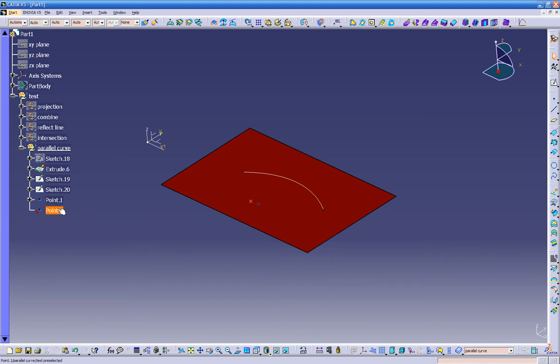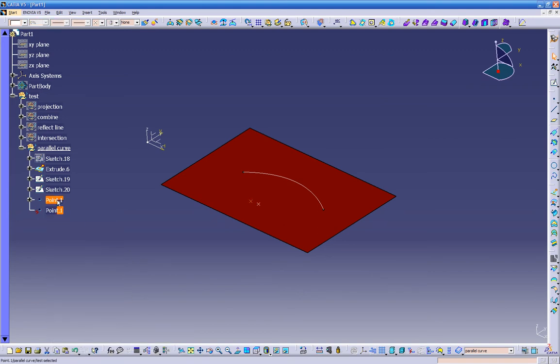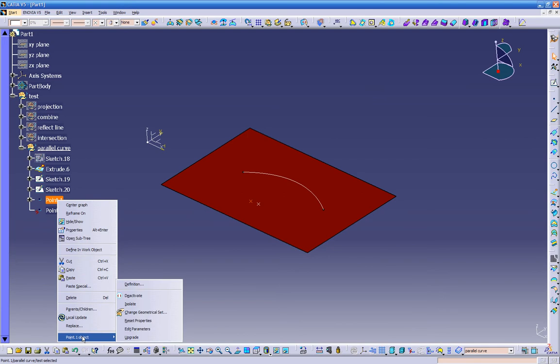So it's all standing alone. That's why when I build my geometry, I want to make sure that everything is linked together, because if I don't like this, I can just click on my sketch, edit it, and then automatically it's going to update my model. But once you break the link, we're gonna have a little bit of problems.